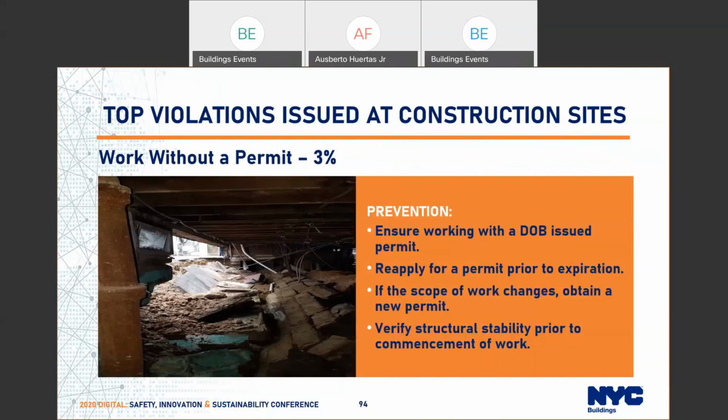Preventative measures include, but are not limited to, ensuring you work with a DOB issued permit and reapplying for a permit prior to its expiration. If the scope of the work changes, obtain a new permit, and verify structural stability prior to commencement of work. Now we will learn more about workers' rights.